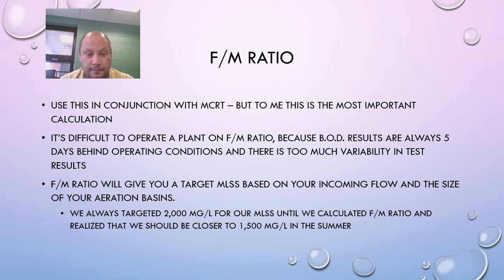So just as an example here at our plant, with all 3 aeration tanks in service, my aeration tank volume is close to 2 million gallons. I know from past experience and from the history of the plant that our mixed liquor suspended solids is usually 70% volatile.